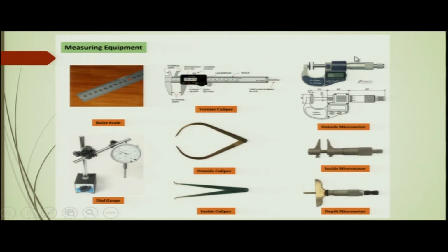Similar to that, for measuring the outside diameter, okay, we can use the micrometer, and here you can see in the micrometer the display which is digital. So, in that case you do not have to read the main scale and the vernier scale and find out accurately what is the measurement, but in this case the measurement can be seen in the display of the micrometer.